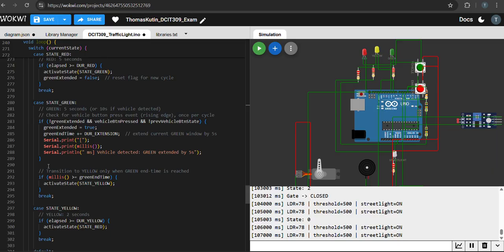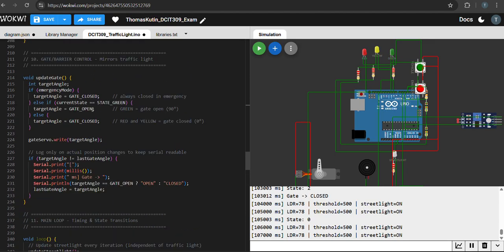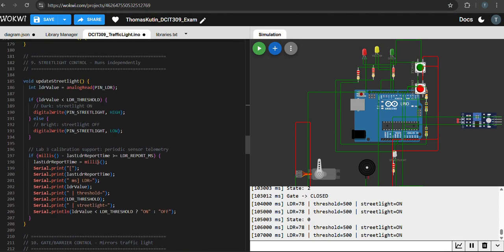And for this loop to run smoothly, we have what you call a millis function. Instead of the delay function that freezes everything, the millis function makes everything run smoothly, right? So that's basically what the millis function does. It's an improvement on the delay function.